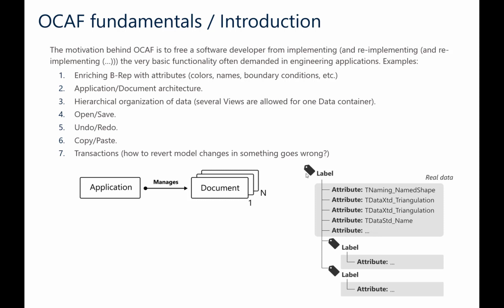In OpenCascade there is a huge set of standard ready-to-use attributes to store your shapes, triangulations, and also primitive types. But if you wish, you might want also to implement your own attribute, and this way to avoid the necessity to decompose your custom data onto the standard elementary chunks.